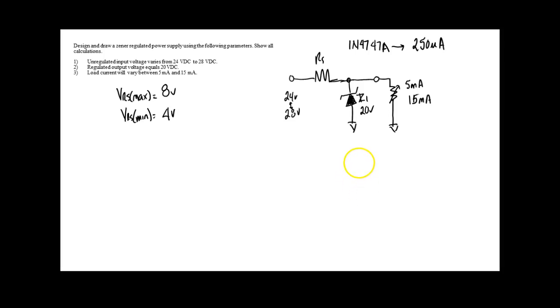Yeah, so what we've got here is, and I'm going to go back to this circuit right here. Just think about the Zener being this bottom resistor. Say this guy here is dropping 20 volts, and I've got 28 volts applied. What would this resistor drop? According to Kirchhoff's law, the sums of the voltage drops in a series loop has to equal the applied voltage. If this one is dropping 20, I've got 8 volts applied. What does this one have to drop? It's got to drop 8 volts because it's got to equal 28 volts.